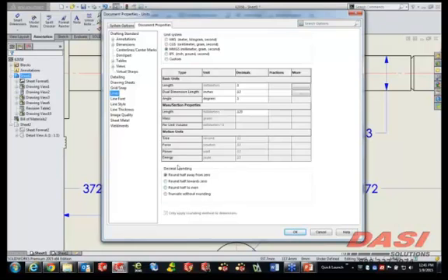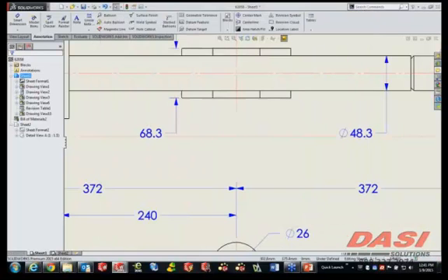Now, each of these values, in some cases, is going to result in rounding up. So 0.25 would actually round up to 0.3. And you get my drift. We're going to round up on anything that could be above 0.0. So if it's a 0.1, we're going to round up. The reason we do those kinds of things is because in wiring and piping, you'd always want to cut it longer than it needs to be, never shorter.